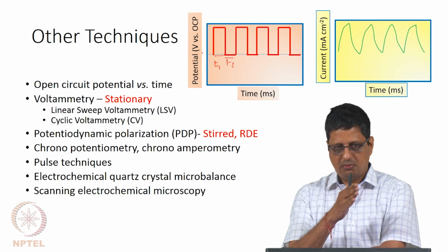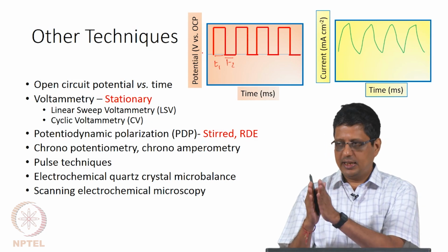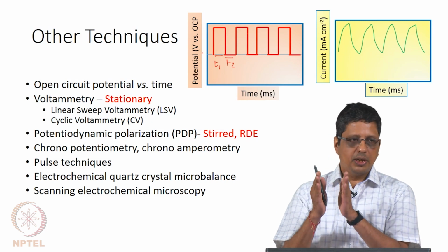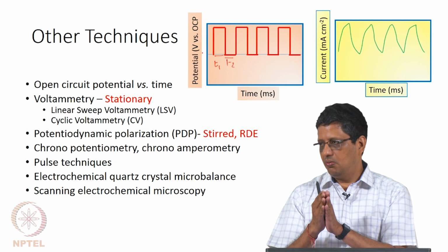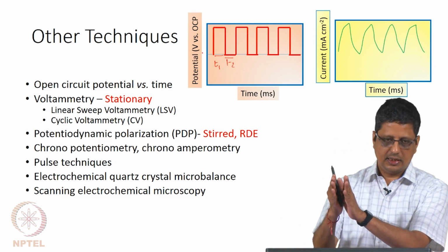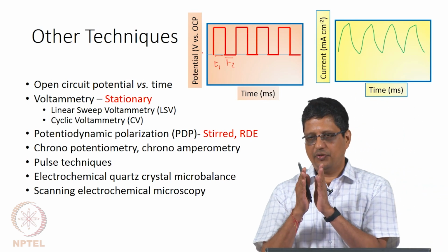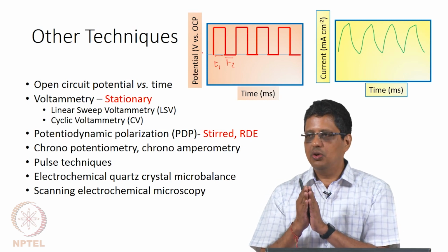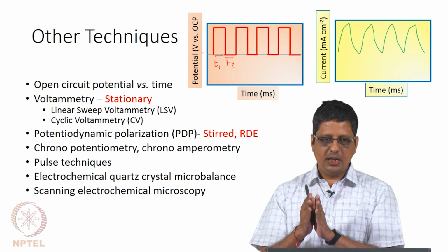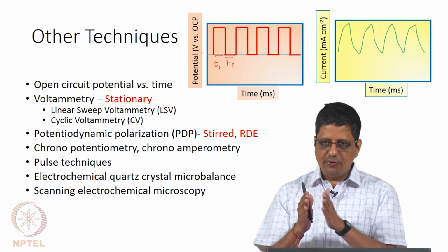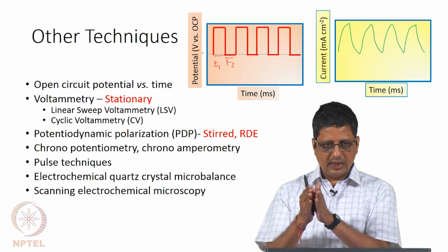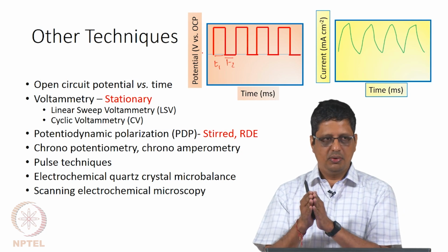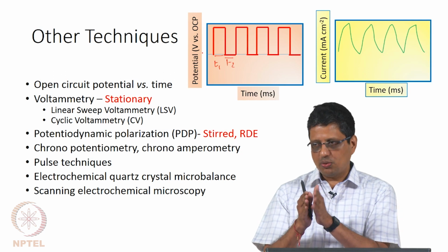Normally, we want to deposit a material to some thickness, we want to finish it fast and then move on to the next sample. But the quality of the deposit may not be good. You can run it at a constant potential, you can run it at a constant current. In both cases, many times you would get a sufficiently good quality, it is fine. Sometimes you may not get a good quality because diffusion may be slow. So, deposit something, then give a pause for the material to come by diffusion, again deposit, that is one way.